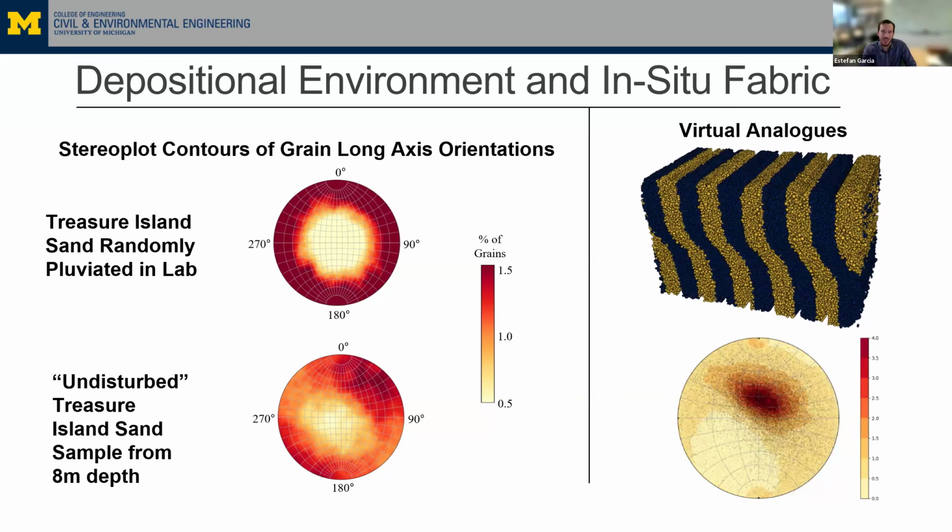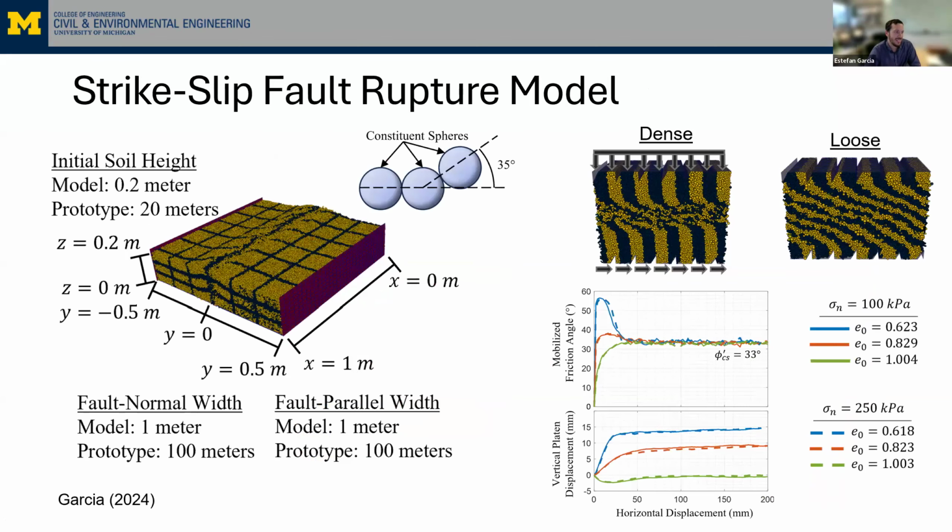Now, I'm going to transition up to a larger scale and allude to what Gareth will present shortly. These simple shear simulations can provide the stress, strain, and volume change behavior relative to shearing induced by nature, such as during earthquake surface fault rupture. And in this work, we're focusing mostly on the component of fabric associated with the relative density. The discrete element method seamlessly captures the salient features of shear deformation in loose and dense granular materials. We can see that shear deformation in this dense material is quite localized, whereas in this loose material, it's quite